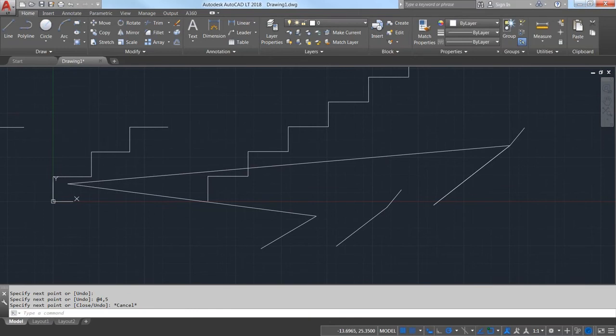Now, one other thing that I wanted to cover, and I touched on it briefly, is the concept of your function keys turning the various snap settings on and off for you. And that is true. So what you'll see, if you hover over anything that has a function key equivalent, like grid mode is F7, if we hit F7, we'll see that the grid toggles on and off. Hopefully with the screen you can see that there. And you can see that the icon turns on and off.